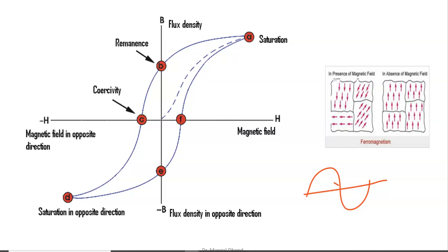And you will see that the material will get heated, and a magnetic humming sound will also be there. So when one cycle of applied current is changed, meaning the magnetizing force is changed, one complete loop is exhibited. This is one complete hysteresis loop. And 50 hertz frequency means that in 1 second, 50 hysteresis loops will be traced.